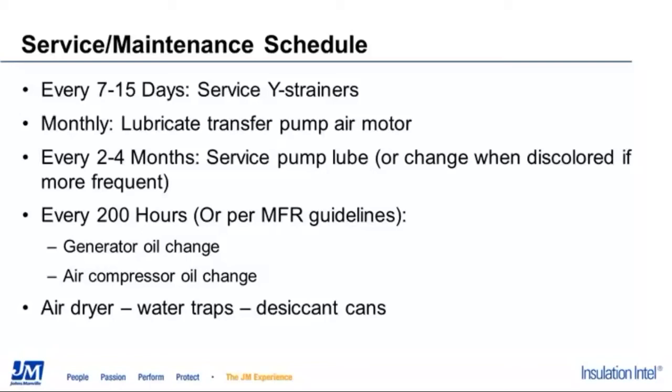On T3s, these are the latest, greatest transfer pump. If you're not familiar with them, the reversing switch on T3s is on the outside. It's not part of the air motor, and it's a much more positive reversing. We've been very, very happy with these new style transfer pumps, but they don't have this element of service where you've got to take it apart. However, on T3s, we could be getting some pneumatic oil like used in nail guns or staplers, and just putting 2 or 3 drops in the inlet for the air, let's just say every 3 days or twice a week.